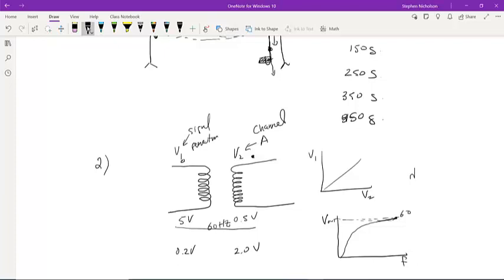We need to generate some dΦ/dt. dΦ/dt is the change in magnetic flux, which is changed by oscillating the frequency, and the more oscillation we get, the more dΦ/dt we get. So in the US we use 60 hertz. In Europe they use 50 hertz. Nobody uses anything less than 50 hertz. So that's the next thing, is we'll look at voltage as a function of frequency.